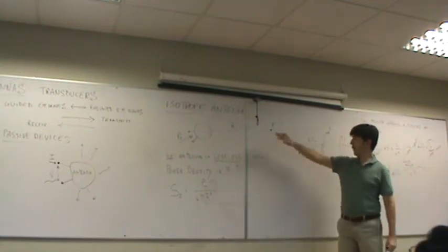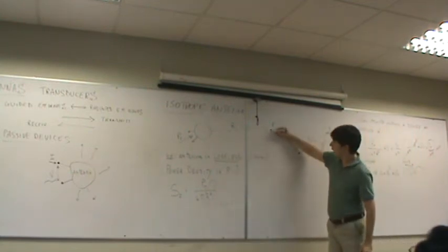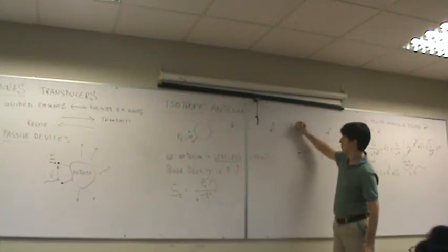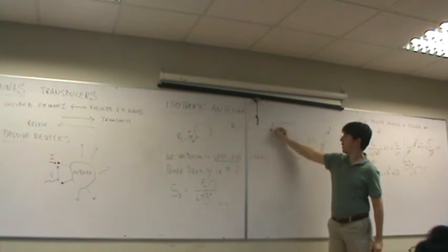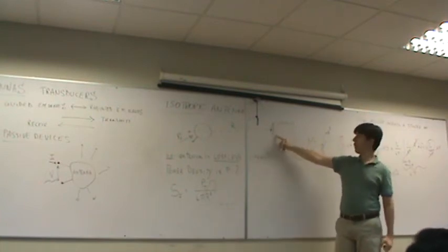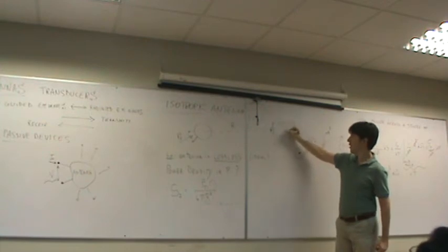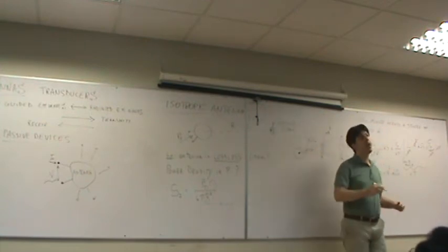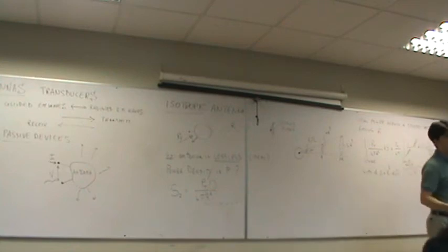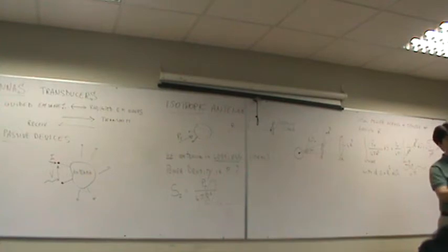Because if you are very far from the antenna and you just look at a small area, the area of your interest, you can assume the spherical wave to be locally plane. We know it's not plane, but if you don't move too much around that point, the wave can be considered to be plane. So you can apply all the things that we know for plane waves, which are easier than spherical waves.